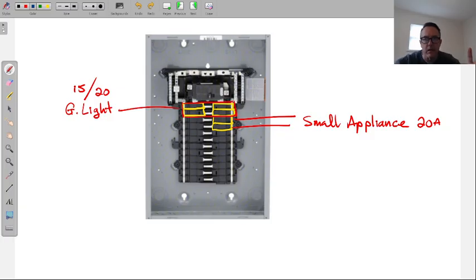I'm buying a freezer for my garage, big amperage freezer. Okay, yes, something like that. But you just want to add a circuit, and it's not that big of a deal to add this circuit. I should just tie it into another breaker. But what people do is they don't want to do all that. They just add another breaker to the panel and then run my outlet. And then sometimes in the future, same thing. They were going to add some new thing that could have already been thrown on another breaker. Instead, they just add another breaker. And so eventually we're full.